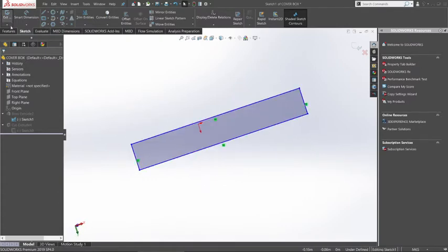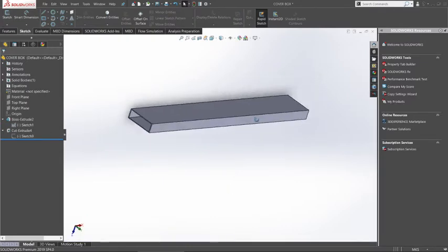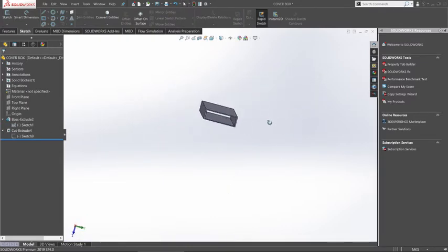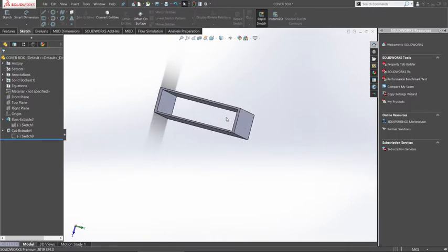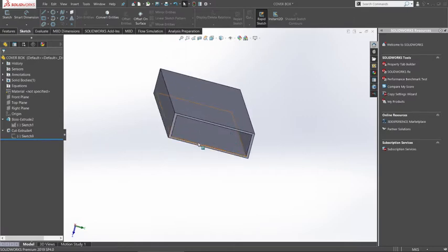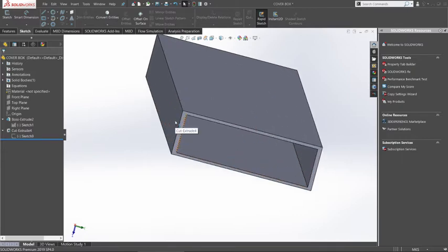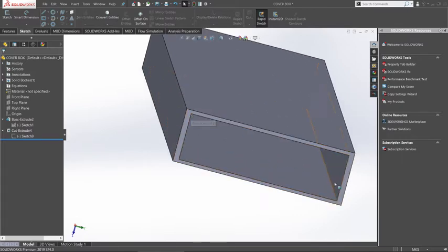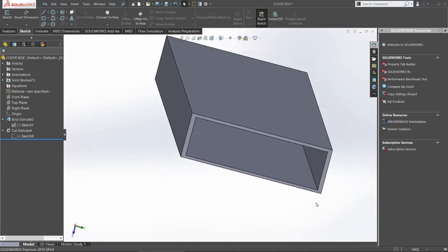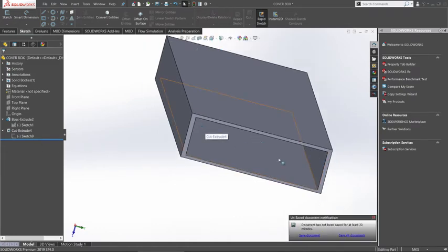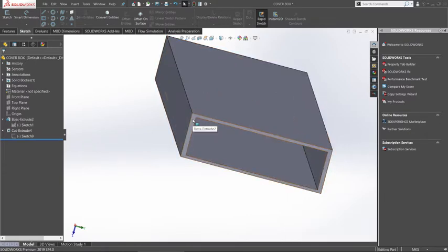And then what I did, I'll show you, I put the thin feature. You can see the duct is hollow, which it has to be, because I have to place a solid body inside it. But what I'll show you is there is some cut extrude here, which should not be here, because I just told you I had put cap ends on here. When you are boss extruding, there is a thin feature, and along with the thin feature there come cap ends. I had to do a cut extrude, if you can see there, which is how I did it.